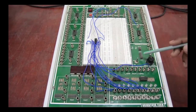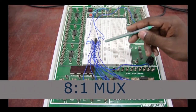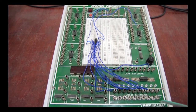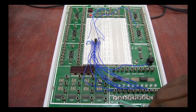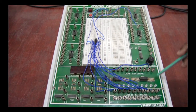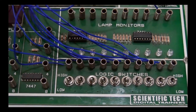And this is the circuit of an 8:1 mux using IC 74151. Here we have 3 switches as the 3 select lines S0, S1, S2, and the rest of the switches are the data inputs, and the output is connected to the first LED. Now we can go through the working of this 8:1 mux.